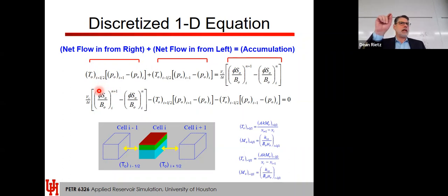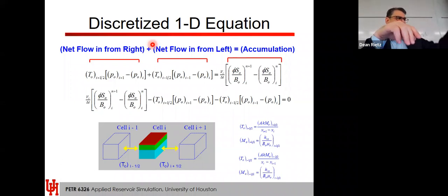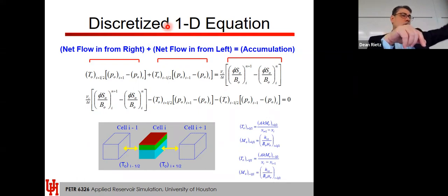I should say that all our calculations are assumed at the cell center. The reason that's important is everything occurs at the cell center. So if we have, let's say, a square cell here and an elongated cell there, the transmissibility is going to be whatever is between the two cells. It's just whatever is the transmissibility of that cell face. If you're using permeability, you have to use the permeability that's effective in that distance from the cell face. And the same thing with the transmissibility as you go from that cell face to the cell center on that side.